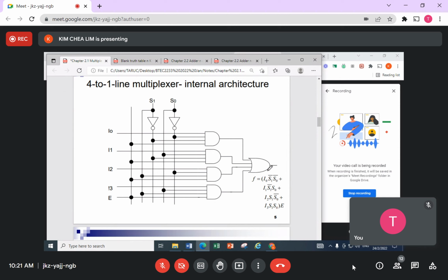All right. So how to build this circuit in terms of hardware? I must build an output which is ANDed together, this function, another output ANDed together, third and fourth, both ANDed together. So look at this one here, my I0, and these both are barred.